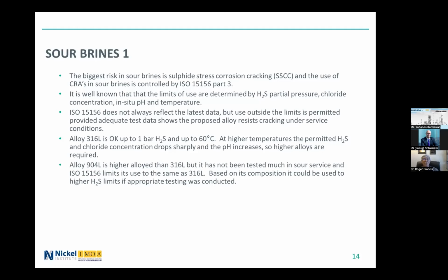Now, alloy 904L is a higher alloy than 316L, but it has not been tested much in sour service, and ISO 15156 limits its use to the same as 316L. Based on its composition, it should be possible to use it to much higher H2S limits, but you've got to conduct the appropriate testing before you can do that.